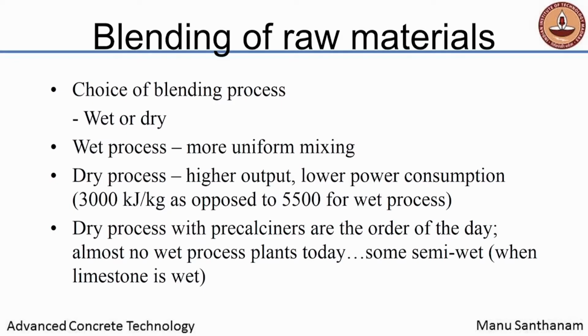Now, obviously when you mix powders in a wet state, you can assure that the mixing is more uniform, the blending is better. When you mix powders in a dry state, you need to be doubly sure that you have mixed it thoroughly so that there is an intimate mixture of the materials. Now, obviously since water is being used in the wet process, a lot of the energy that is spent in the kiln operations will be spent towards drying off this water, removing the water. Whereas in the dry process, you do not have that problem.